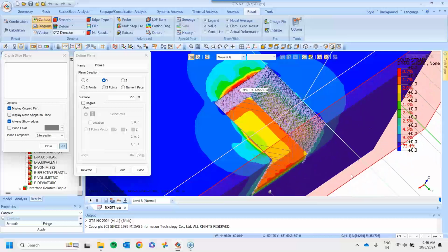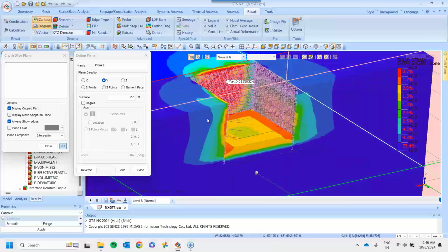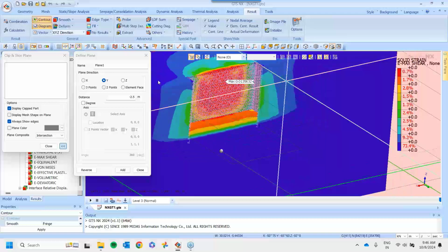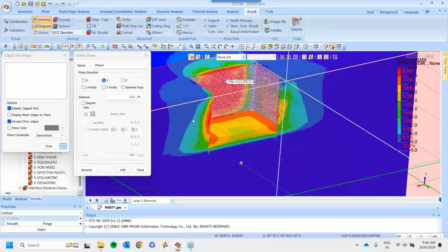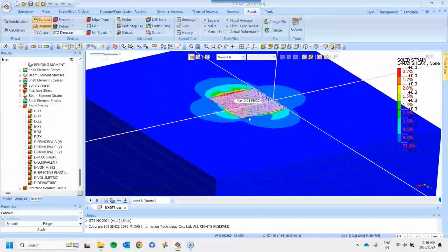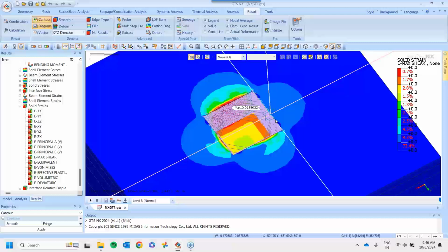So this is how the excavation looks like from the Y direction. And you can see the shear zone formation along the boundary of the wall and the retaining elements. So basically, we can say that thanks to the support system in here and also thanks to the ground material in here, whatever excavation was created, the entire impact is contained very close to the vicinity.